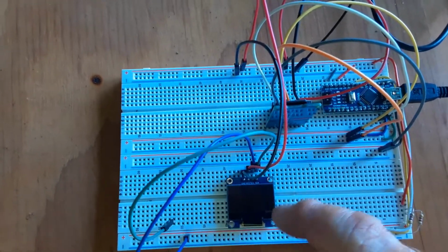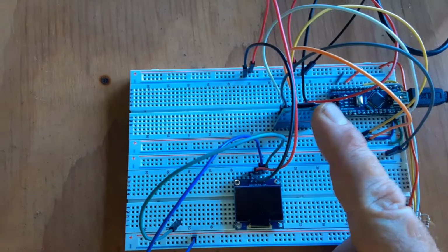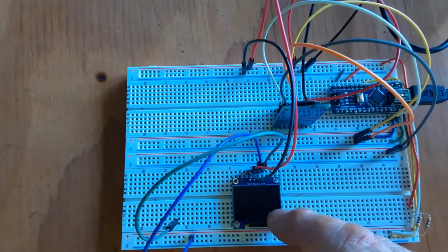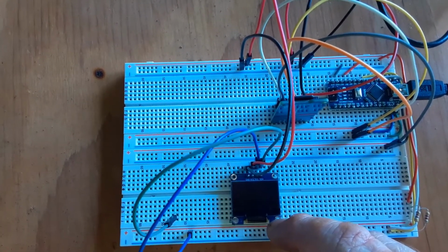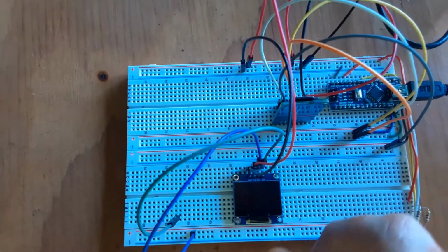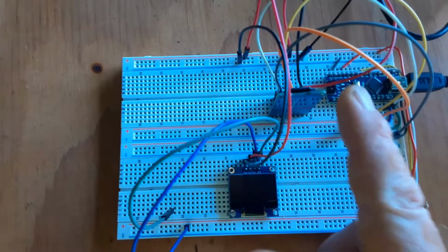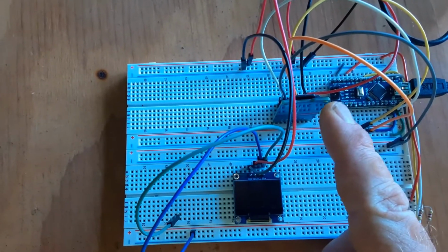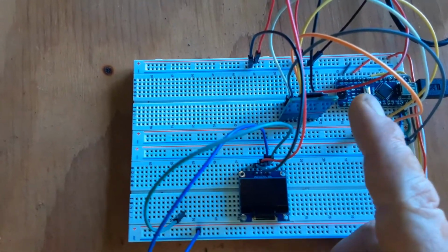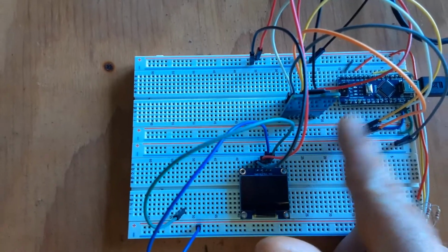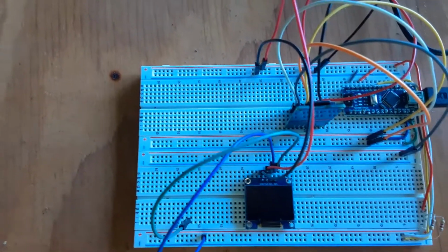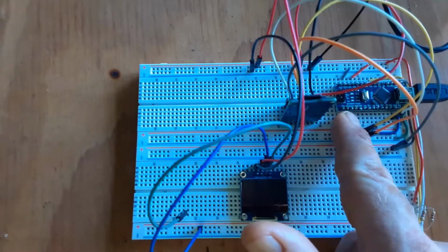And the libraries I generally would prefer to use with both SD card readers and OLED screens both try to reserve a bunch of RAM so they can do more, especially the graphics on the OLED. And putting them together, the two that I prefer to use want more RAM than an Arduino offers by itself.